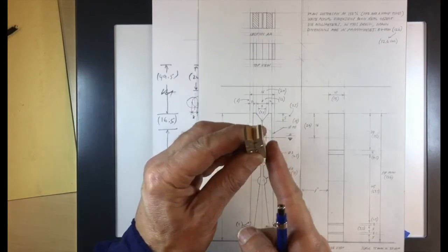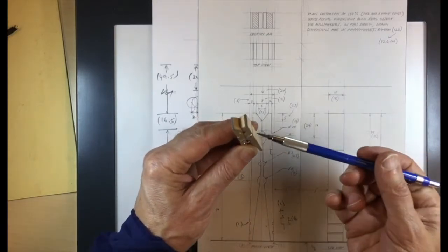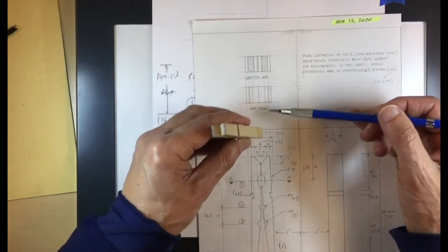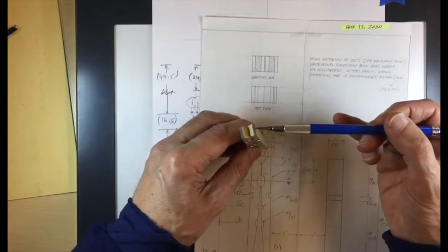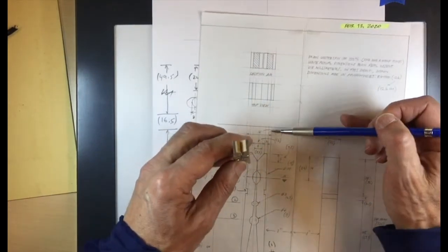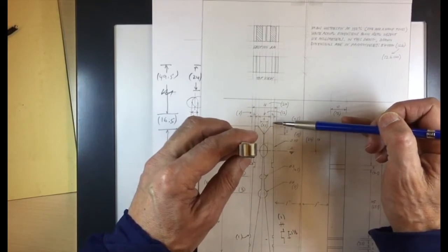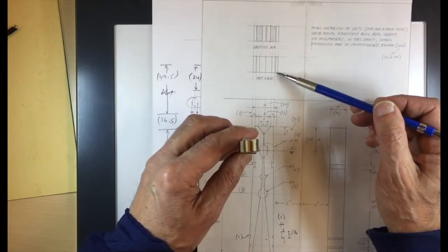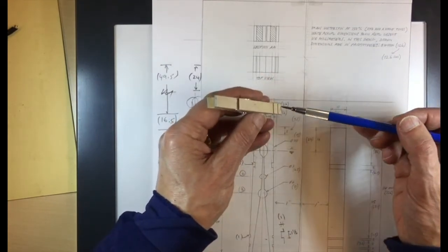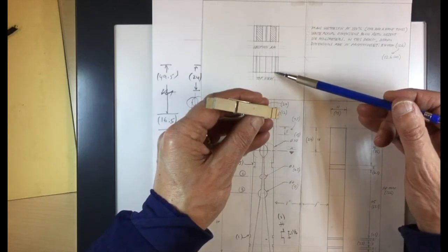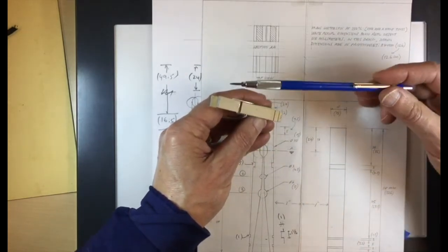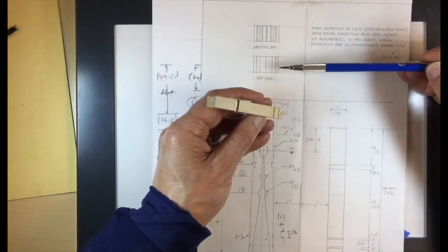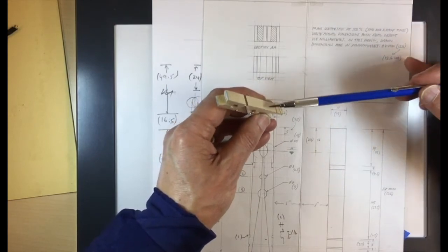So in other words, when I project the corner of my tip, which is this spot, I get this line right here. So between this point and this point, I have the entire pin. So this line representing this, and this bit representing that, in that small space, in theory, I'm supposed to represent also these notches, but in practice, as you can see, I just did perhaps this one with maybe a very faint double line.